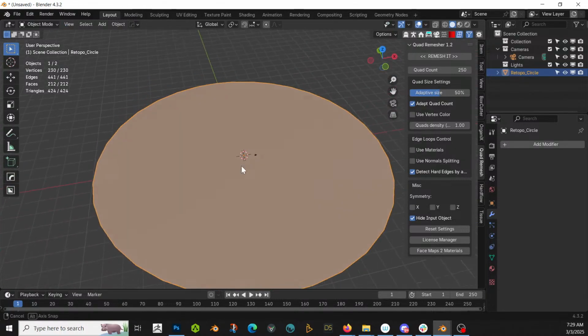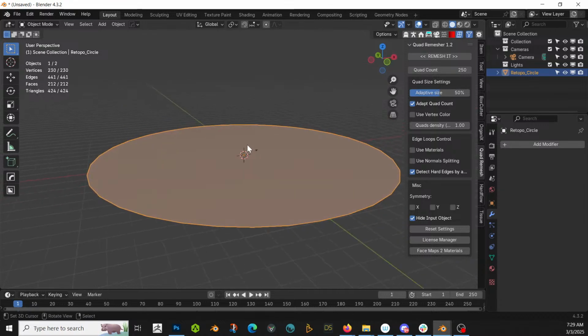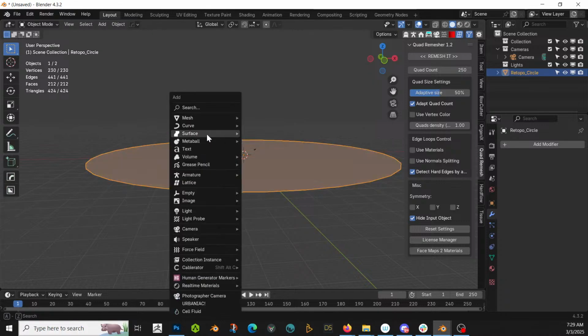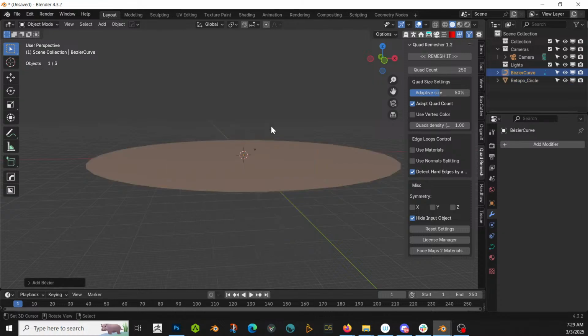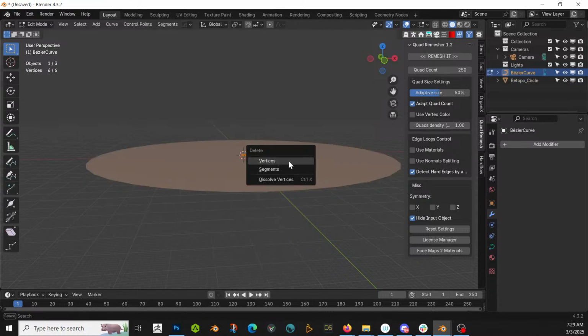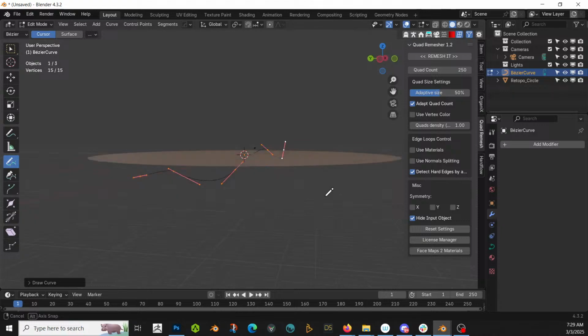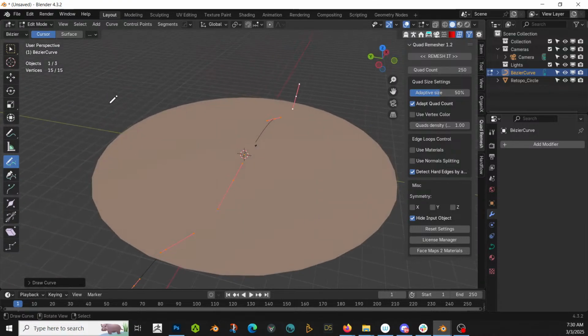And we want to put a road down the middle of it, but we do want to have some terrain sweeps to it. I don't just want it to be a flat ground. So let's play. I'm gonna draw first with draw terrain. Bezier, tab, X, vertices. And we're going to just draw. We don't want it to go terribly big, but just a little bit of sweepy, like that. Okay. That gives us enough. We can start and then we can edit it.